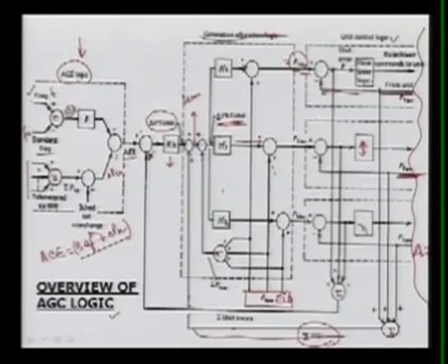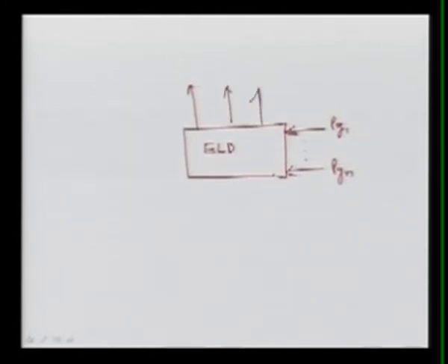It is nothing but we just solve the economic load dispatch, and let us see how it comes. So here the P base, the output I will show in the next, I will just draw a block. Here this is your economic load dispatch. We measure the current PG1, and all the inputs are measured by telemeters, meaning from all the generations we get the inputs that we measure. Now here we do the economic load dispatch. We know the total demand of the generation, and based on that the output of this ELD will be what is called P base. This economic load dispatch is normally done every 3 to 5 minutes, and then the P base is set. So this is called the economic load dispatch logic.